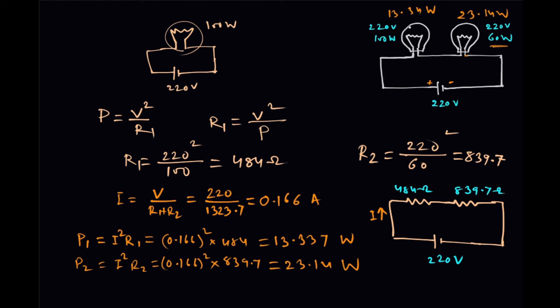That means for parallel connection, because in the household you will find the two conductors. This is positive or negative, you can say, or phase and neutral. In the AC case it is phase and neutral. So all the loads are connected like this between these two. These are connected in parallel, and the supply is from the utility supply, that is the supply from a power company, distribution company.